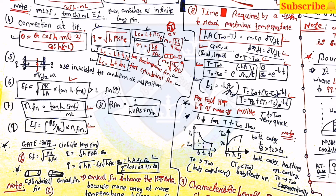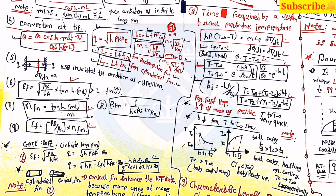Then (T minus T infinity) divided by (T naught minus T infinity) is equal to e raised to minus hA upon rho CV into t. So you can say that theta by theta naught is equal to e raised to minus Bt. This equation is also very useful. Then T is equal to T2 plus (T1 minus T2) into e raised to minus Bt.